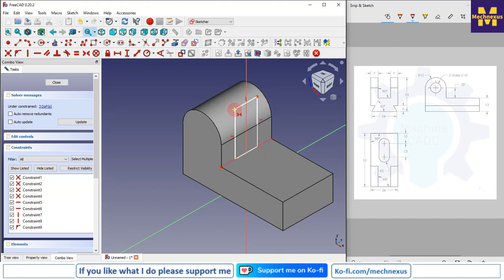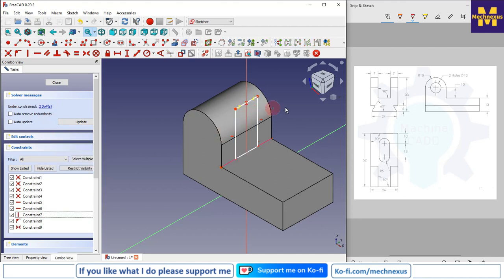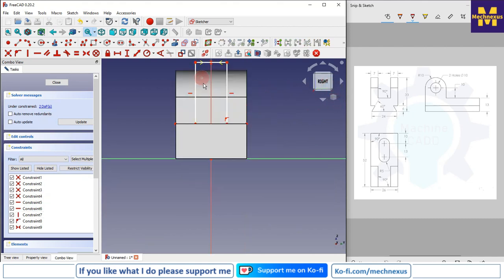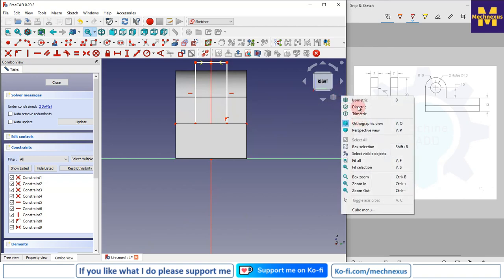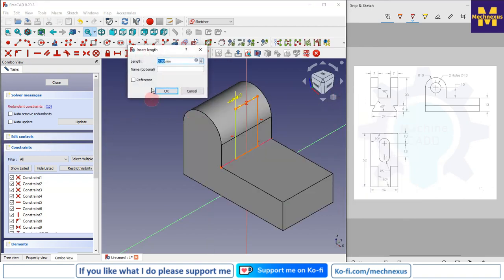So for this I will select this point, I will select this point and the axis. So here is a conflict, so click on this number 7. So constraint 7, I will delete it. So this will be the through all material removal. So overall height doesn't matter, but still we will give the dimension.